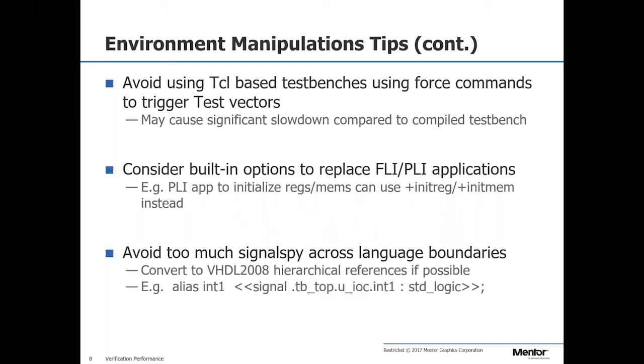The next thing is, if at all possible, write your test bench in VHDL or Verilog or System Verilog. Don't do a bunch of Tcl-based force commands. It's just super slow compared to writing a test bench in your verification language.